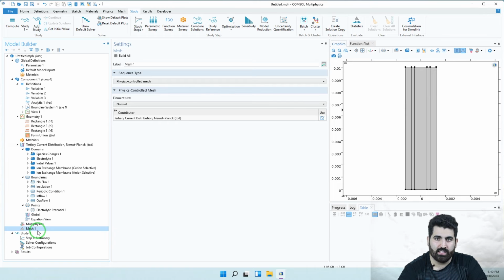You must consider this fact that mesh is very important, because all the formulas, all the equations, all the gradients and derivatives were solved on this mesh, and a wrong mesh causes infinite solutions that cause problems for running, and your solution will not converge.